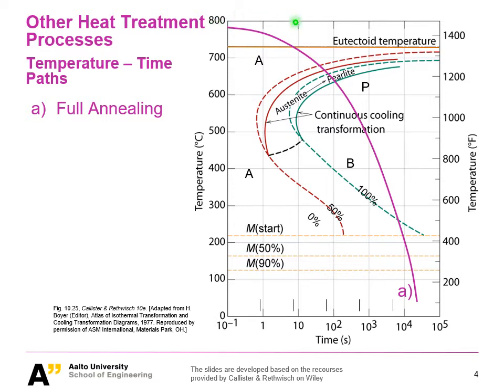This is the slowest possibility you could have. And of course, you can imagine in the end, for our case here, we will have a pearlite phase, even a pearlite phase with very coarse grains, because the cooling rate is very slow and you won't have too many nucleation sites, so therefore you're going to have rather large pearlites.